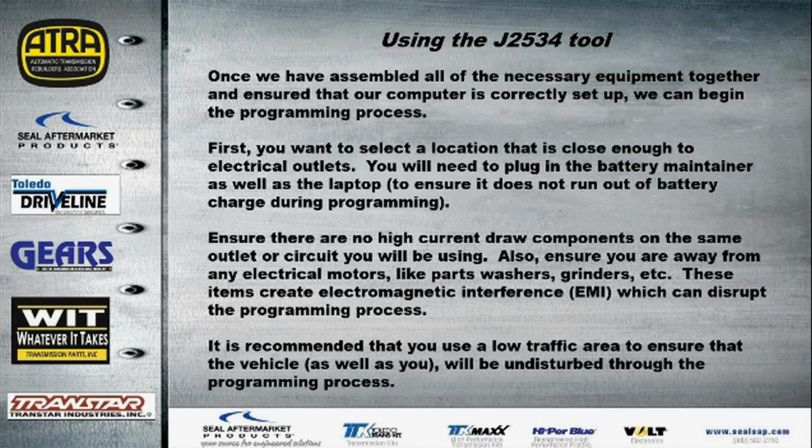Basically, you also want to be in an area where you have access to a clean power supply. In other words, you don't want something like a refrigerator on the same outlet or circuit that you are trying to keep your equipment plugged in on, because you want to plug your laptop in. You don't want to run on battery the whole time, because if you go low on battery, you don't want that to stop the programming process. Also, we're going to have a battery maintainer plugged in as well. So we want a clean wall outlet supply.